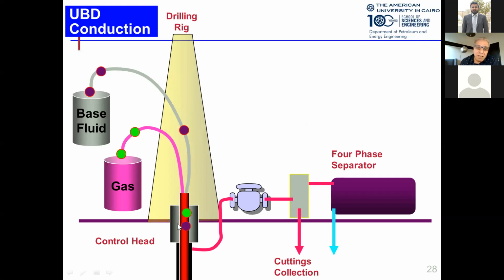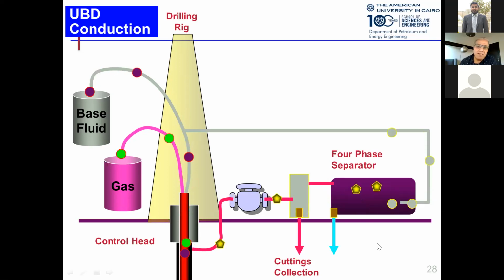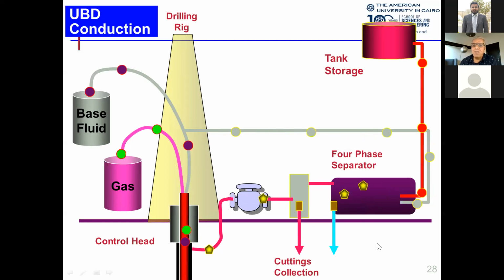When they reach the bottom area where we drill, where the cuttings are coming, the cuttings along with the drilling fluid come back, and the main cuttings are taken over a shaker, and the fluids go to a separator, where they get separated. Water gets separated there, the drilling fluid goes back for reuse, and oil is stored. Of course, this is a very initial treatment.